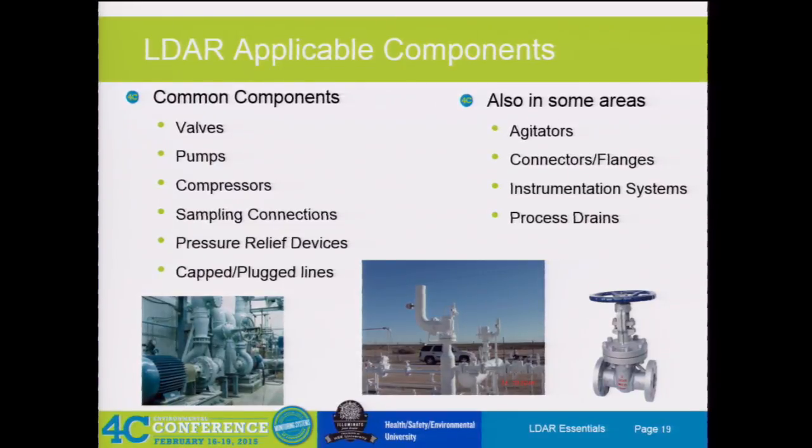What is process? In the rule, I'll pull it up for you, but it says it must be double block, capped or plugged. The downstream valve is shut before the upstream. It's because no matter what, you cannot have process fluid on a single seat. So you have to close the upstream first to move it to the downstream valve, so that it's purged between and you actually have two seats before it comes to the opening.